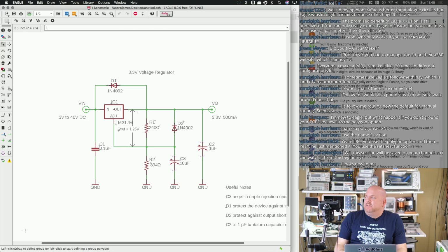And actually, now that I think about it, the PCB layout might be useful for certain things like a switching regulator where you've already figured out the optimal layout, or maybe the oscillator for a microprocessor. But outside of that, you probably end up moving things around. It still would have been nice if you could have a basic block you just drop into both the PCB and the schematic. So that's kind of cool.